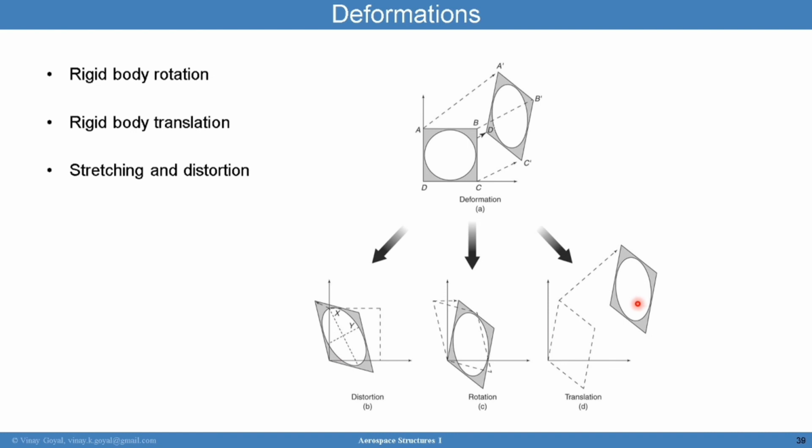So it's really important to understand that strain is a quantity that's useful because it's going to account for rigid body rotation and rigid body translation. And that's not going to affect how much it moves or deflects. It's not going to affect the real straining behavior of the part, which is a quantity that really matters because it's directly related to when failure could occur.